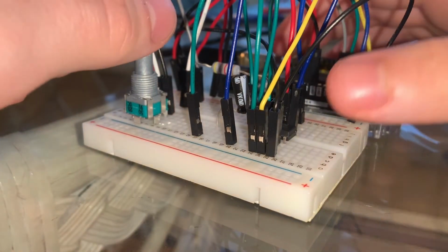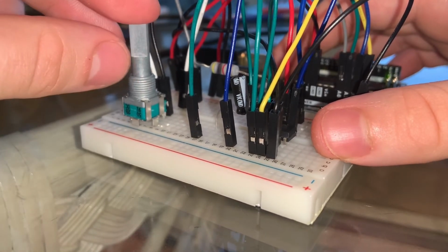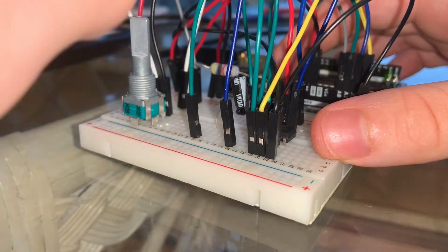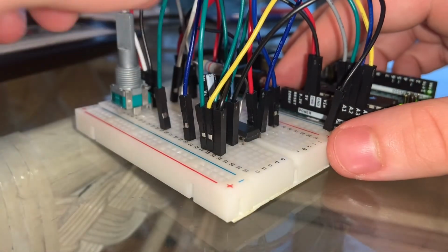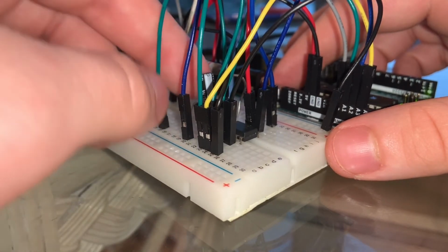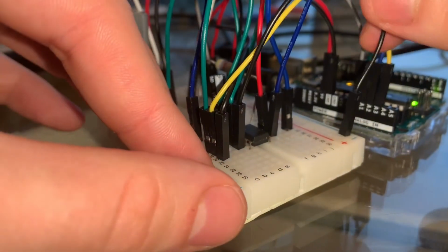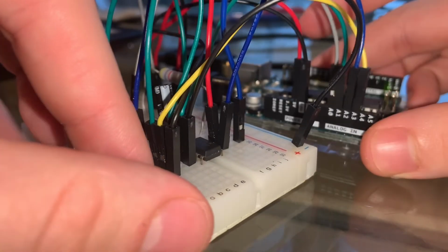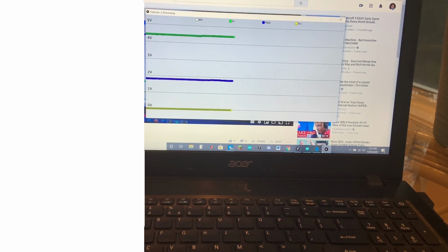All right, so finally, we're just going to analyze our circuit here for exercise 4. We have the V in being supplied by the potentiometer, going straight through the resistor, and then going into V minus, and then from V minus going out through the capacitor and into V out. And then V plus is just grounded, and all the pins here are the same. Now, I just wanted to note that for exercises 3 and 4, I used the same processing and Arduino codes as 2 because nothing changed between the exercises for that.